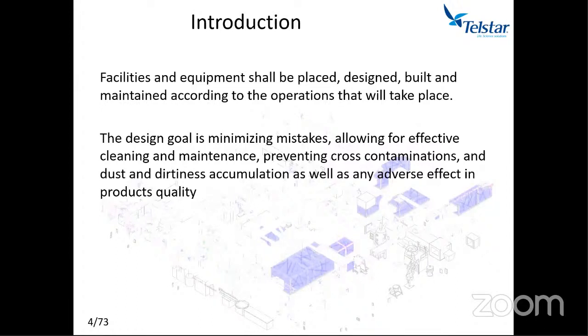If we talk about a lyophilizer, today you only have inside the clean room the door where you're going to be loading, and it is just what we call a slot door, a very small door, so that everything gets into the area. All the rest of the lyophilizer is outside the area, and that helps in doing the operations and maintaining the cleanliness of the area.